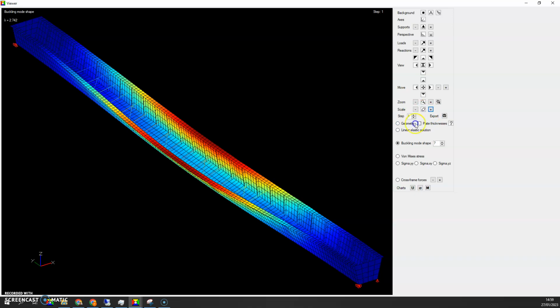And it's at 2.7, when we can recall that without top lateral braces, that mode was at 0.8. So we've increased the eigenvalue by a factor of 3. This is a huge improvement in the stability of this tub just by adding 8 members, 8 bars, 4 at each end.